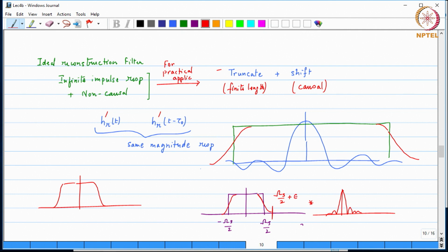This is the main reason why right from the beginning we were saying do not do exact Nyquist rate, need to over satisfy the Nyquist criterion, because any time I need a reconstruction filter, the windowing based filter is probably the easiest way to do that. Why?